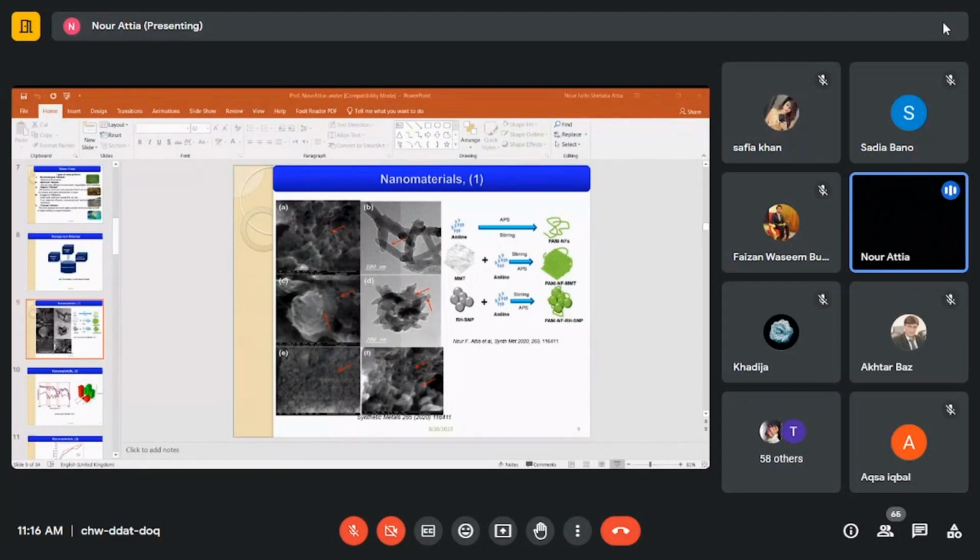The metal ion is already completely dissolved. You cannot see it in the water, right? And you have an adsorbent, and the adsorbent is nanoscale, right? So if you are designing a material and adsorbent for wastewater treatment, and you know what you are doing, then you will design some active sites at the surface of the adsorbent, right? So you will functionalize active sites on the surface, and the active sites will be distributed on the surface of the material, right?